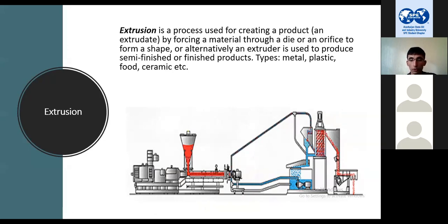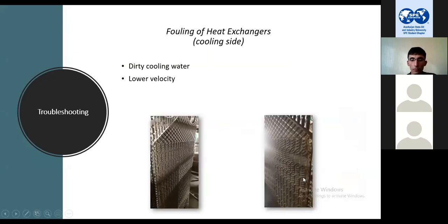It works with cooling water to cool down this water. This is a photo from when that exchanger was full and didn't operate normally. We had to dismantle this heat exchanger and wash it with some chemicals to make it usable again. This photo was taken at that time.